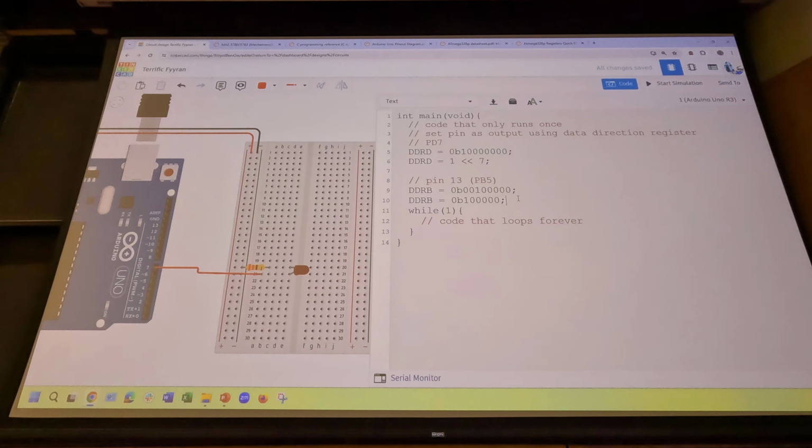Okay. I am going to delete that extra stuff there and comment this out. And again, both of those are the same, in my case, as doing pinMode 7 OUTPUT. That's what this Arduino language command is actually doing behind the scenes, right? All it's doing is setting the corresponding bit in this data direction register high. It's just doing it in a much more user-friendly format and hiding what it's doing in the background. Okay? So everybody have your pin set as an output. Okay, yes?